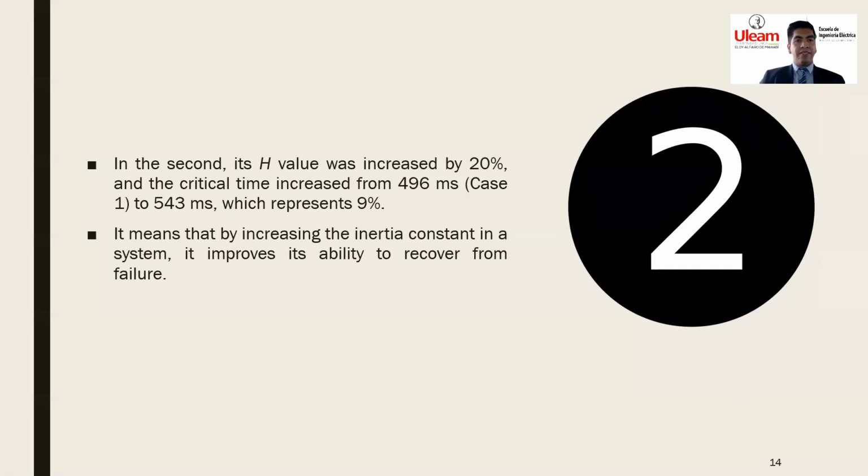In the second, its H value was increased by 20% and the critical time increased from 496 milliseconds to 543 milliseconds, which represents approximately 9%. It means that by increasing the inertia constant in the system, it improves its ability to recover from failure.